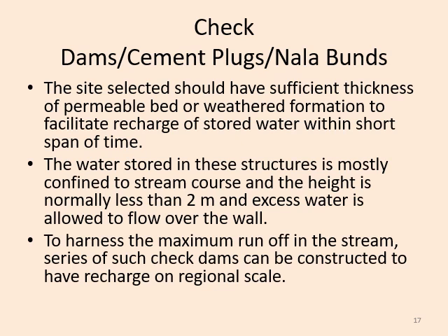Now check dam or cement plug or nala bunds, almost the same. The site selected should have sufficient thickness of permeable bed or weathered geological formation, to facilitate the recharge of stored water within a short time period. So first, the site for constructing this check dam or cement plugs or nala bunds has some factors we should keep in mind: there should be sufficient thickness of permeable strata.